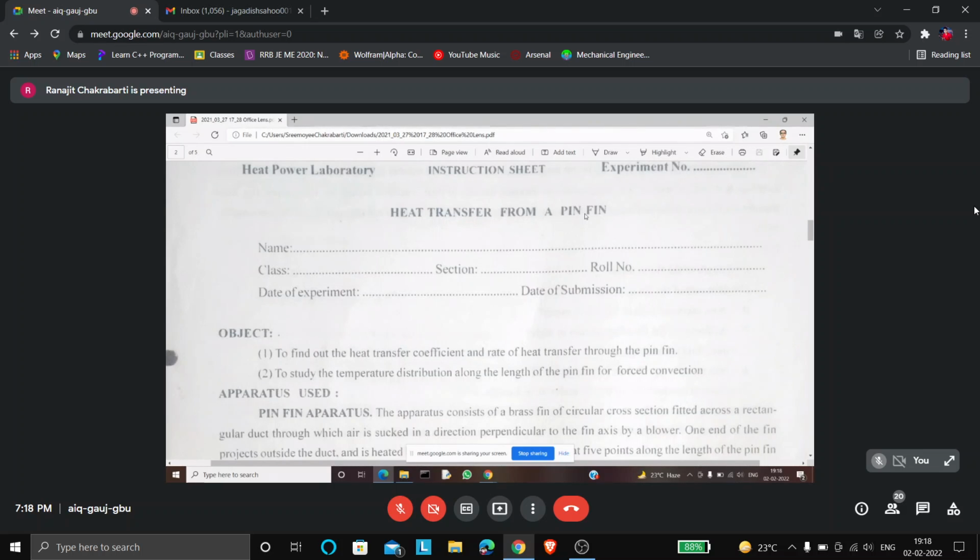Second thing is to increase the H, the convective heat transfer coefficient. That again is also a very difficult thing. We can change the value of H, that is correct, but we cannot increase it to anything we want. We cannot increase it to any level. There may be changes. It depends on the velocity of the fluid. It depends on the Reynolds number. All these things, that is true, but still there is a limitation. We cannot increase it to any level.